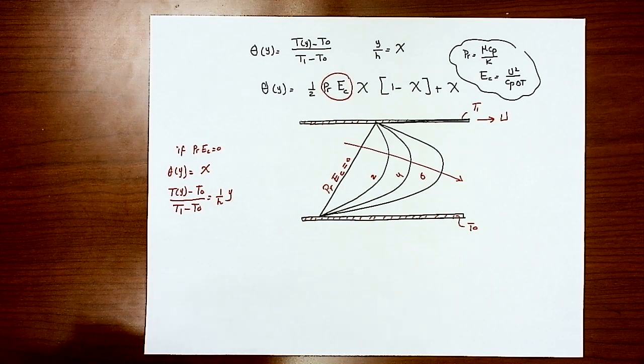Think now if the two plates are fixed, like Poiseuille flow, pronounce it the way that you feel comfortable with. You can change the boundary conditions, but you can still derive both the velocity distribution and the temperature distribution. So this exercise concludes the use of the conservation laws to get the analytical solution between two plates, or Couette flow, with temperature gradients between the two plates.